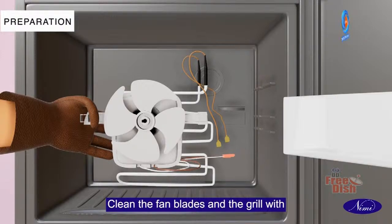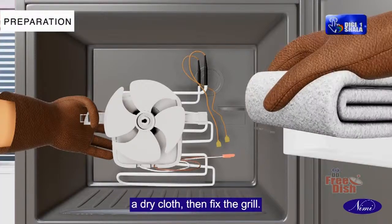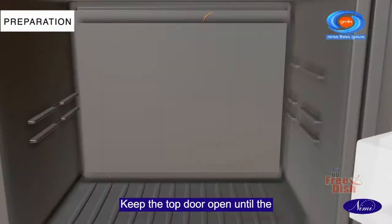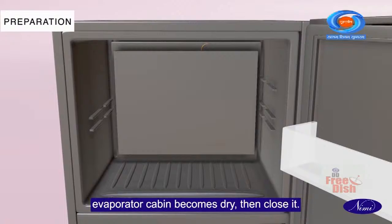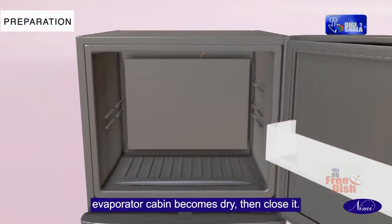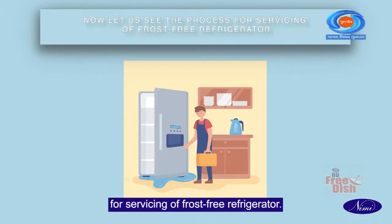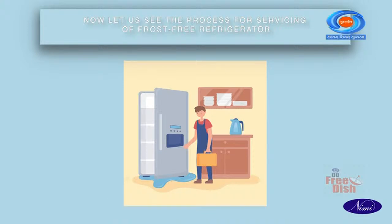Clean the fan blades and the grill with a dry cloth. Then fix the grill. Keep the top door open until the evaporator cabin becomes dry. Then close it. Now, let us see the process for servicing of frost-free refrigerator.